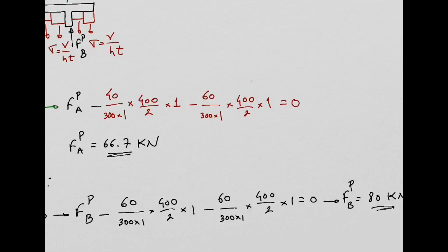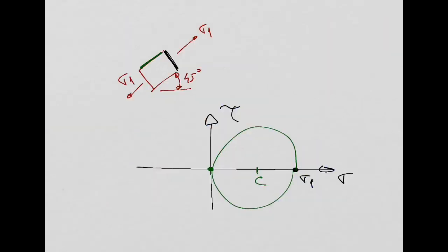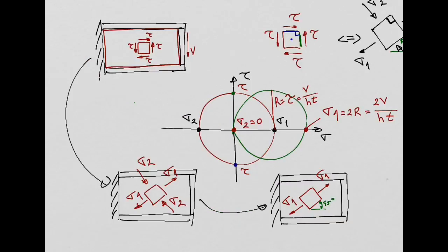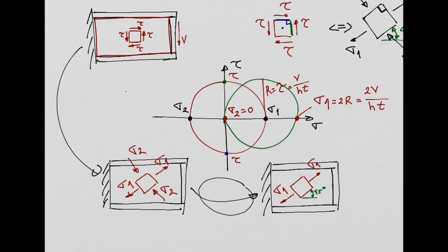I will try to find, because I think there are videos showing this, the development of the diagonal tension field in a spar. Like I said here, in this step from here to here, I told you that the web is going to buckle in this direction too. So I'm going to try to find some videos to show you next week where you can see the web buckling in this direction, number 2. This diagonal tension field developing in aircraft.